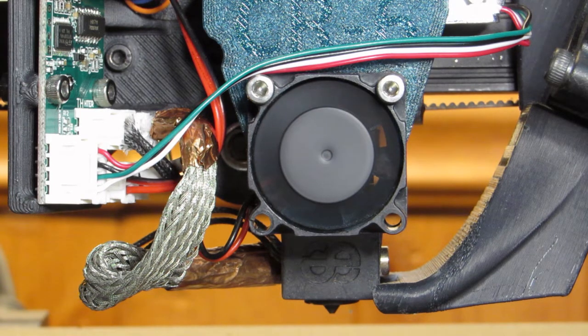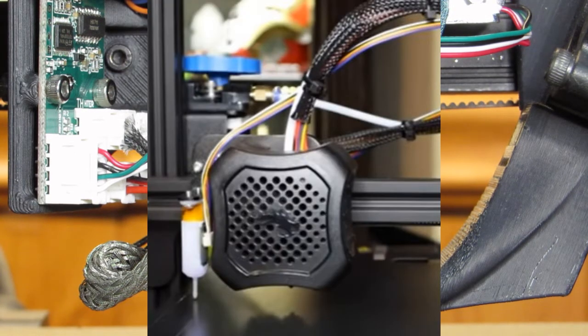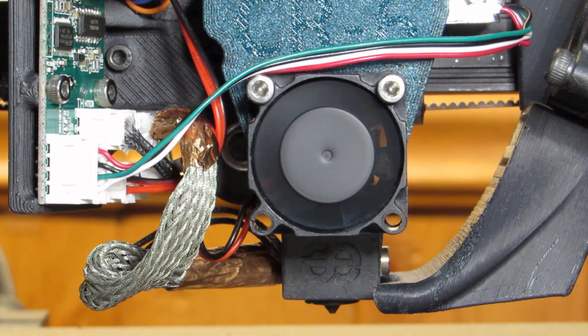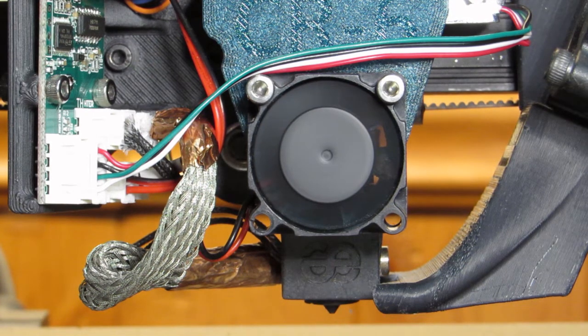It knows which kind of probe you're using, and then it knows what parameters govern the accuracy of that probe and what matters, and it uses the offset information to protect you. Let's say you're using a BL Touch, which is a servo-driven probe. It's got a little pin that projects below the tip of the nozzle when it's looking for the bed, and then pops up above the height of the nozzle when it finds it. Because you don't want the probe dragging across the bed while you're printing. You need to be able to lift it above the level of the nozzle when you're printing, but you need it to hit the bed before the nozzle does when it's coming down probing. Right, makes sense. So those of you who haven't seen a BL Touch before and don't know what I'm talking about, if you look one up now, it'll make more sense to you.